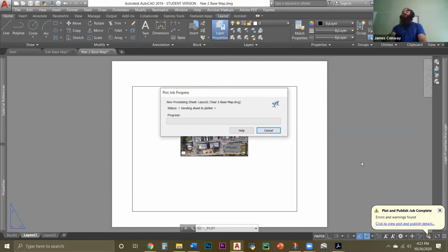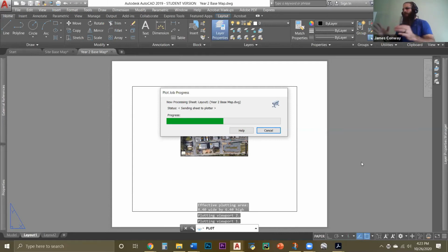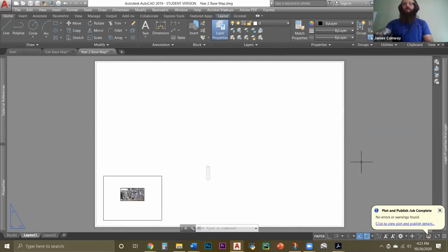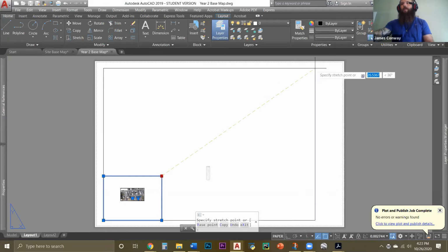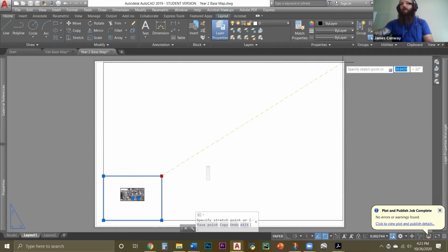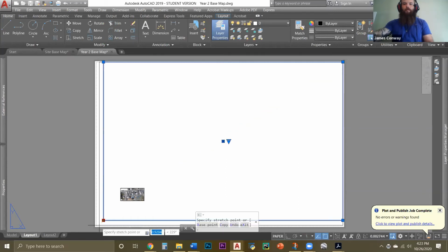Once we get it here, the tracing part really depends on how you want to go about it. You're going to trace over in AutoCAD, and I like to make plenty of layers. I make a road layer, parking layer, building layer, and you can break the building layers down as far as residential versus commercial versus whatever if you want. When you start printing, you can print off layer by layer, as long as you have an outline or a scale or some way to line them up together, and then put that into Photoshop.